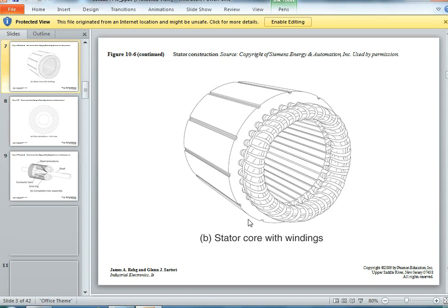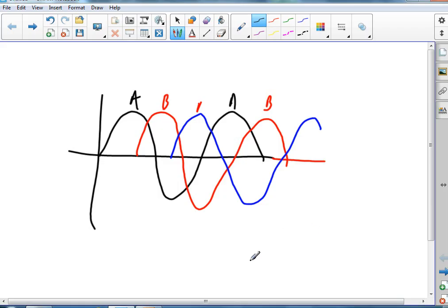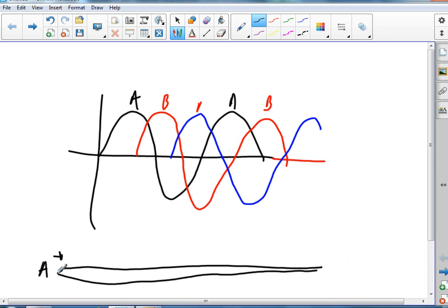Okay. Because here I got a wire, and I got phase A going down it, right? And then I got a wire right next to it with A going down it, and a wire next to it with A going down, and another with A going down. It doesn't matter that they're touching, they all have A going down it. What matters is that they're not touching the housing, they're not touching the rotor. Touching each other wouldn't be an issue because they all have phase A going that way. Right. So there's not much difference.